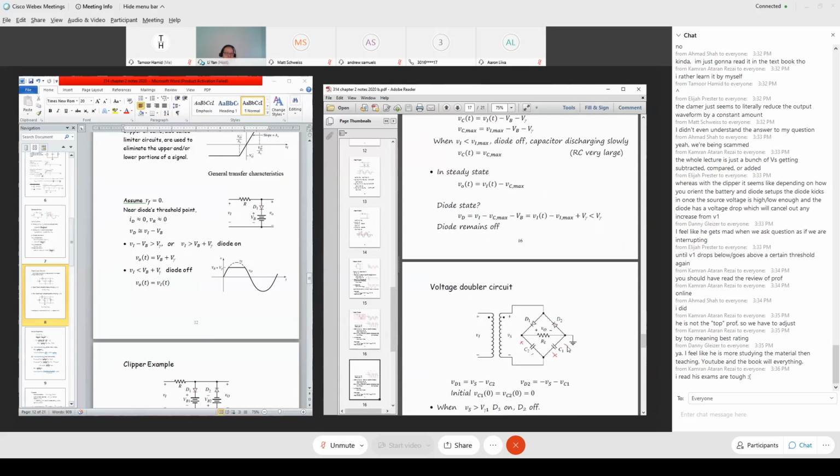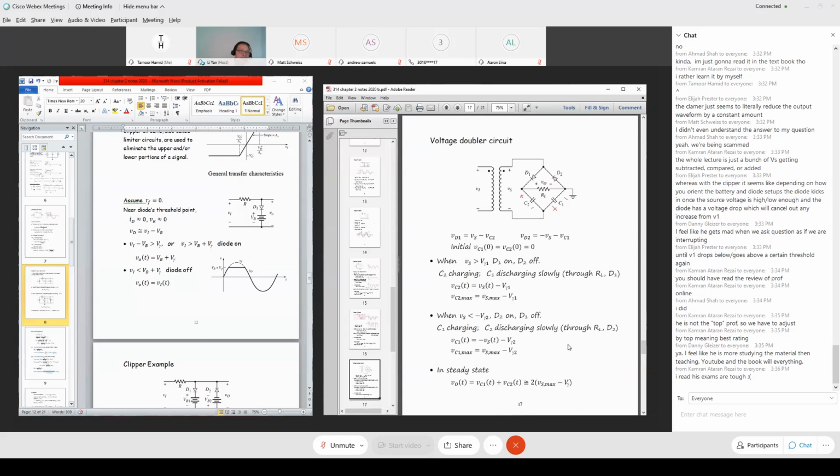Okay, let's look at another circuit. This circuit is a transformer circuit, like in the bridge configuration. However, here we only use 2 diodes instead of 4 diodes. In place of the other 2 diodes, I put in 2 capacitors. And at some point, the capacitors will get a charge. And for the capacitor voltage drops, I define the polarity: VC2 plus minus here, VC1 plus minus there. Okay, capacitor voltage VC1 polarity, VC2 polarity.